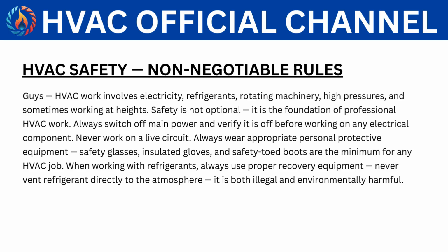Always wear appropriate personal protective equipment. Safety glasses, insulated gloves, and safety-toed boots are the minimum for any HVAC job. When working with refrigerants, always use proper recovery equipment. Never vent refrigerant directly to the atmosphere. It is both illegal and environmentally harmful.